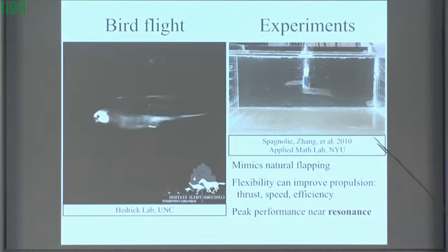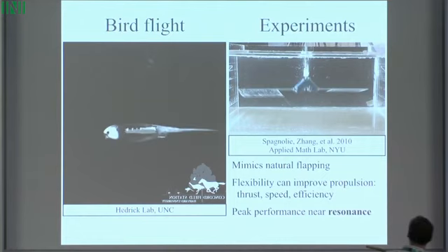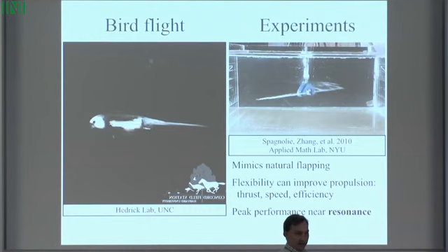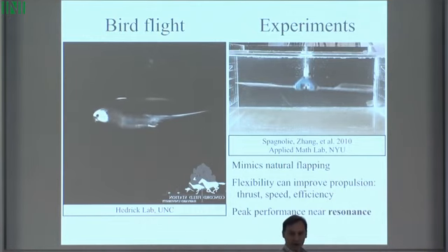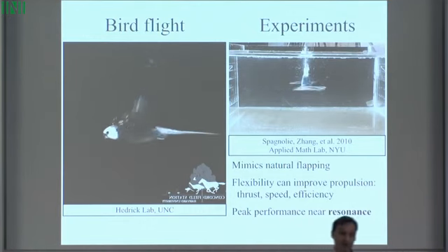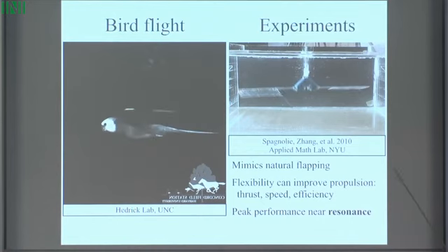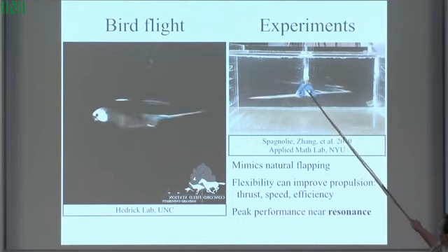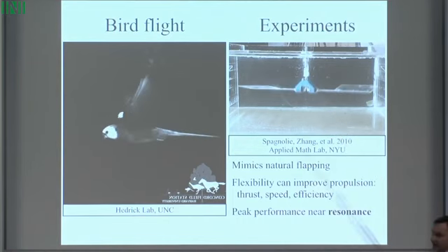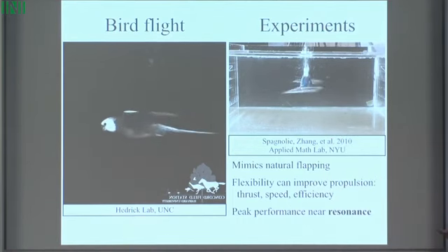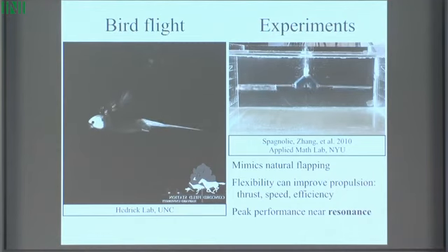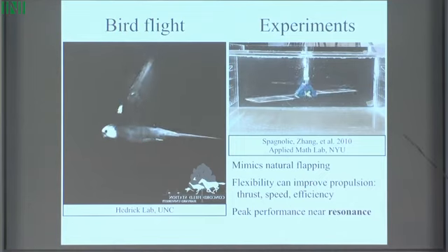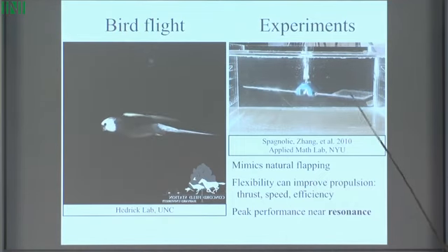The other motion you see is this angular pitching of the wing, and I have the perfect prop here, albeit a bit long. The angular pitching component is also emergent, so that is not forced. That's allowed because this axle here is connected to a torsional spring in this mechanism, which allows it to flex and provides that elastic recoil. So this is the system I'm going to start out by studying.